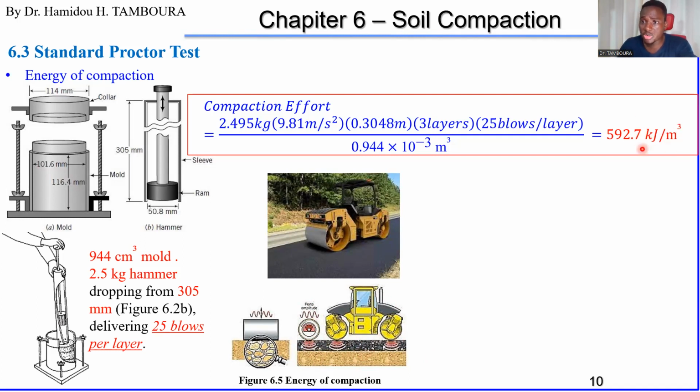But if you know the energy you need per cubic meter, and this is important to specify, because if you know the layer of this soil, this asphalt for example, which is now being compacted, if you know the thickness of this layer, then you know what length you need to go to get 1 cubic meter. So anyway, this is how it is used.